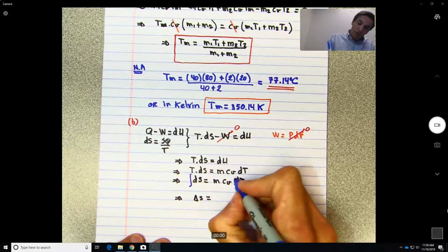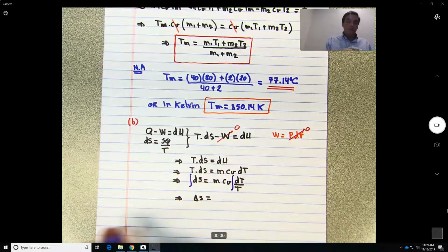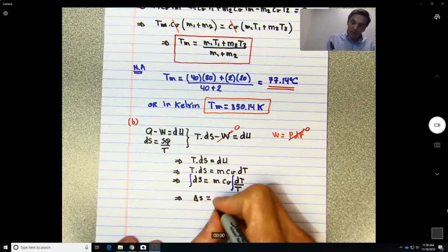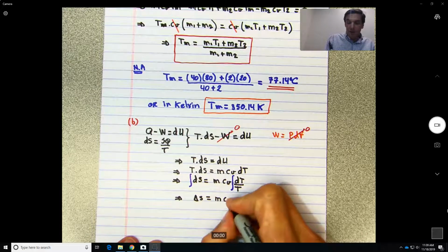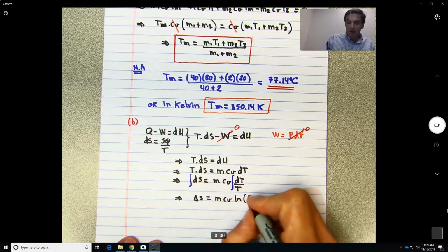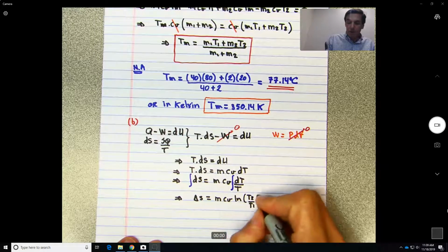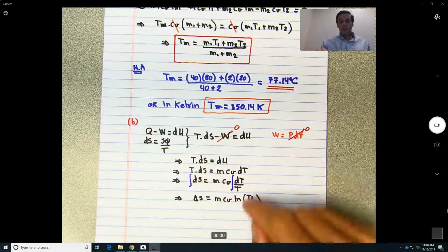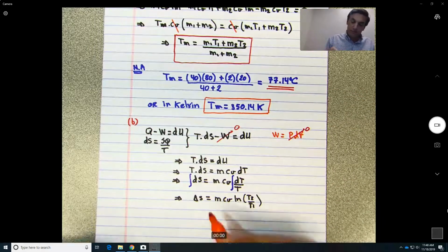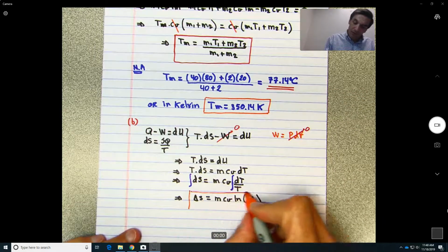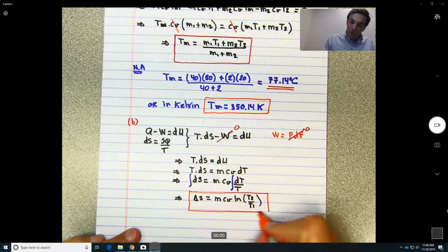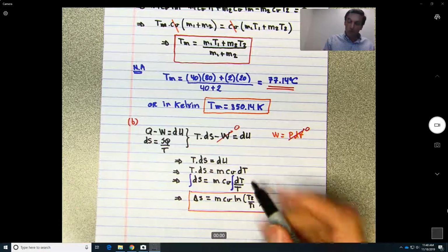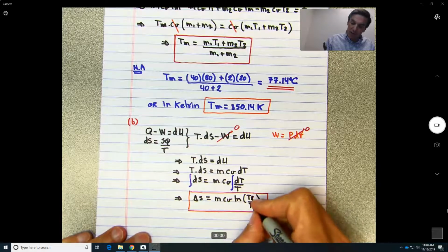and I'm going to be quick over here, but this should be on the previous videos. The change in entropy should be equal to what? m Cv log, let's say T2 over T1. But these are not the T1 and T2 over here, okay? This is a general expression. If you want, call this one T final and T initial, not to confuse anything. So T initial, T final.